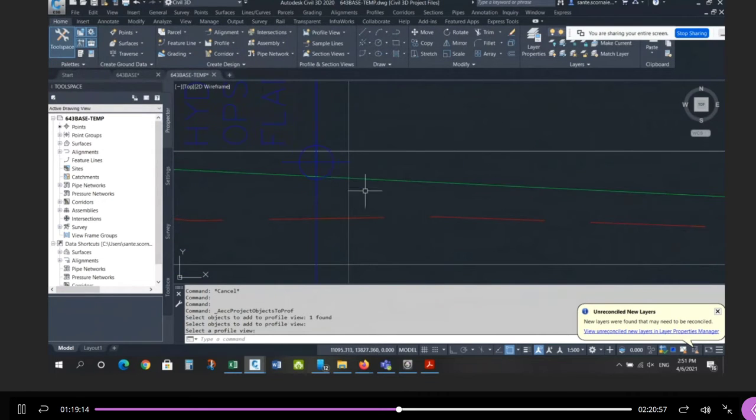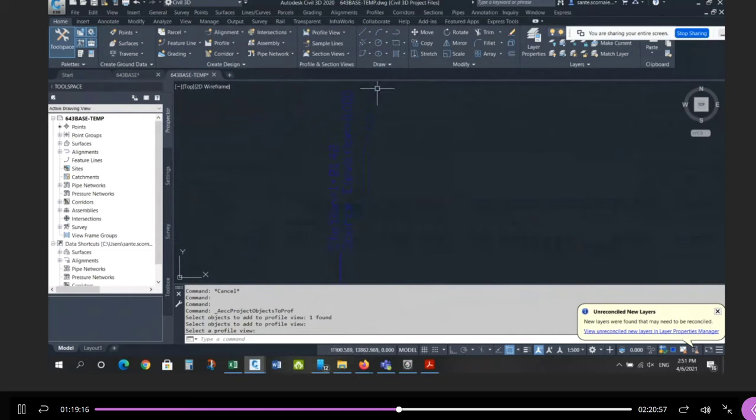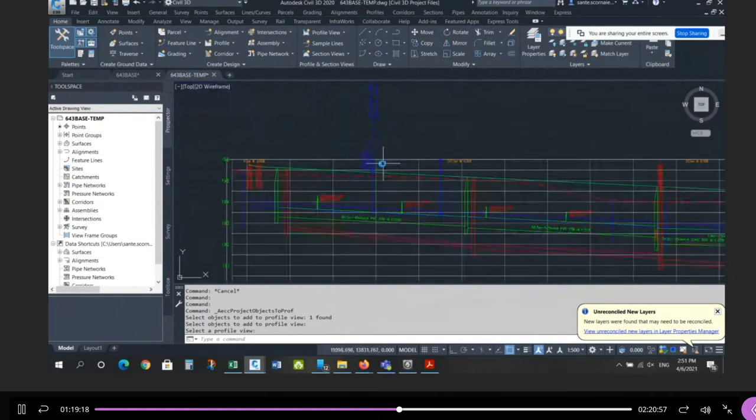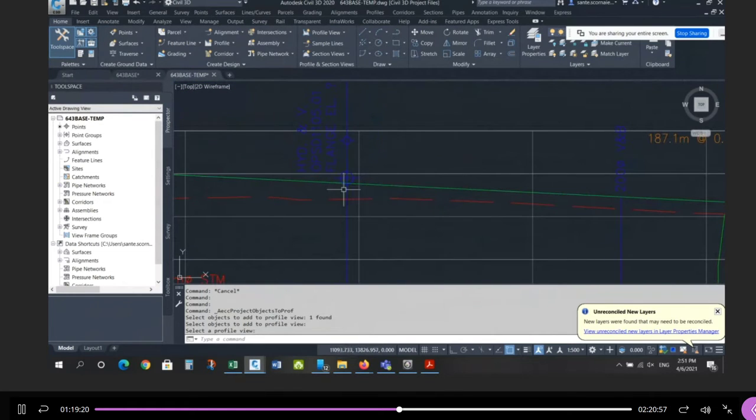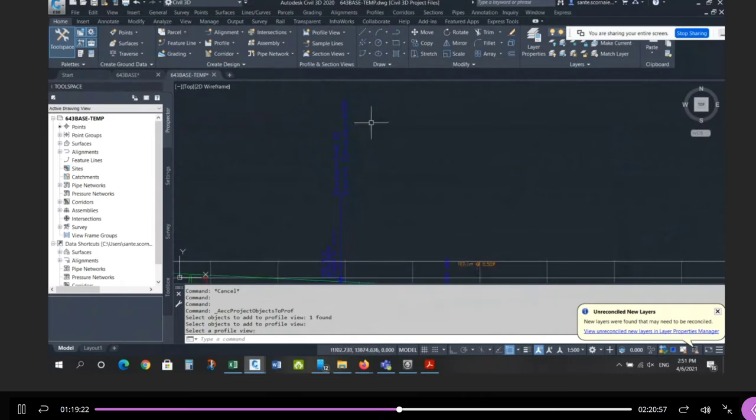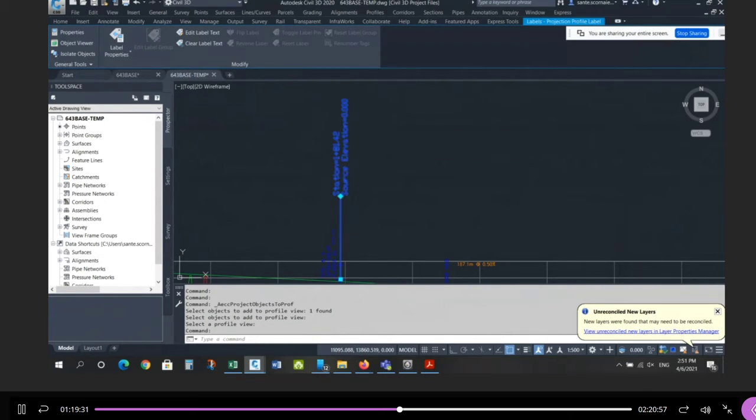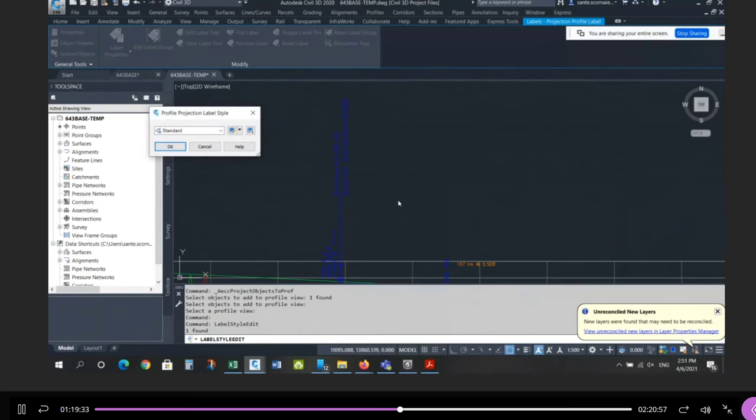Remember, this is the center line of the road. So that's the boulevard elevation. So whatever this elevation is, it's not showing it to me, but whatever this elevation is, I'm going to add 0.15 to it. Okay? Now, the reason you're not getting a number here is because the source elevation is 0. It's in the plan view, it's flat. So it's showing me that. If you want, you can change the style, change the standard style, and again, you can make a copy of it.